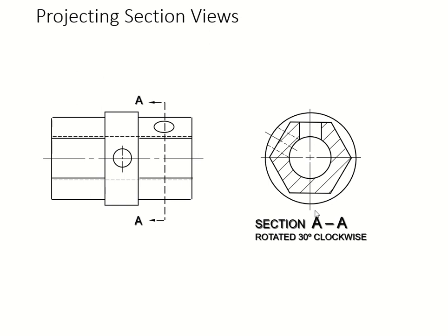Of course, you're rotating 30 degrees, and since you're rotating, you have a direction. We're rotating in the clockwise direction. When you pay attention, you can see this is your circle, so since you cut it down that way and your line of sight is going in that direction, you're seeing the internal features along the reference or cutting plane right there.